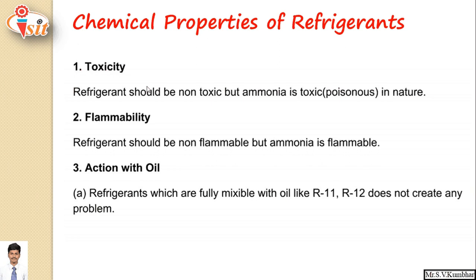Action with oil, as I discussed, in case of miscibility, the oil should not be fully miscible with refrigerant, that is oil should not be mixed, and even if it gets mixed, then its chemical composition should not change. So R12 and R11 do not create any problem for action with oil.